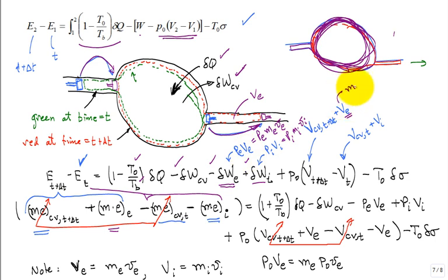That's equal to the mass exit, specific volume exit. Okay. Likewise, this volume inlet, you have to account for here. All right. And that volume we already did. That's the mass inlet, specific volume inlet. And then finishing out, you have this entropy production times T naught exergy destruction term. Look good? All right.